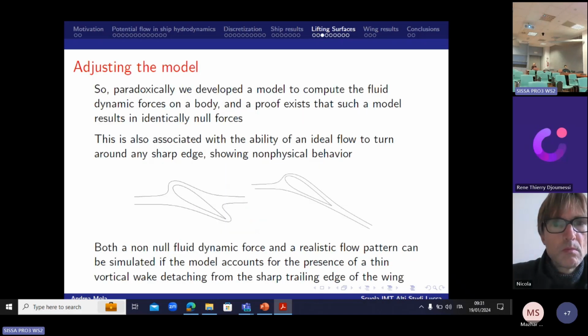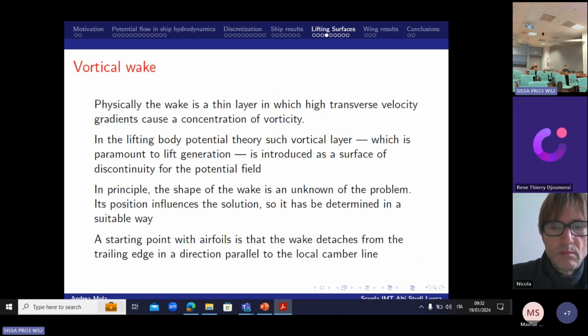The reason why that happens, I think, is shown quite brilliantly by this image. What happens on an airflow like this with a theoretical model in which the fluid has no viscosity and no mass somehow, is that the fluid is able to turn around this sharp corner, come back, and then restart without suffering. I mean, it doesn't suffer for these stiff accelerations, whereas instead in nature, air is heavy and goes completely straight over there. So we need to temper our model just to represent that, and we will obtain good forces even for this kind of flow.